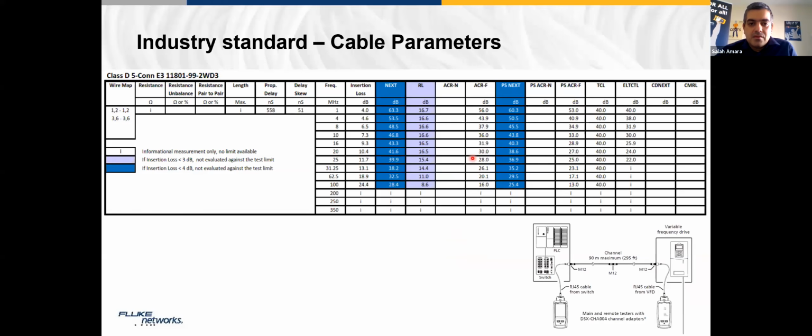A question for Muhammad. I think you answered it, but it's nice to share. What's the maximum data rate we can expect in an industrial control system? It is based on your cabling from both sides and your active equipment also. I think it can be up to 10 gigabit per second when you're going to automation and using the M12 code.